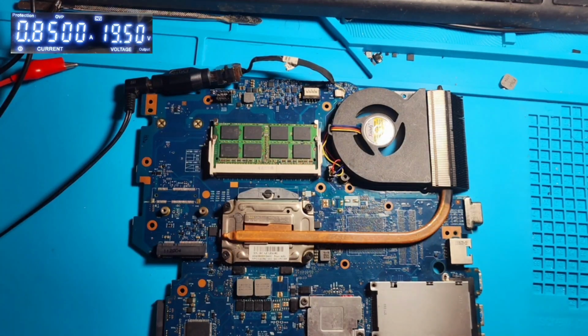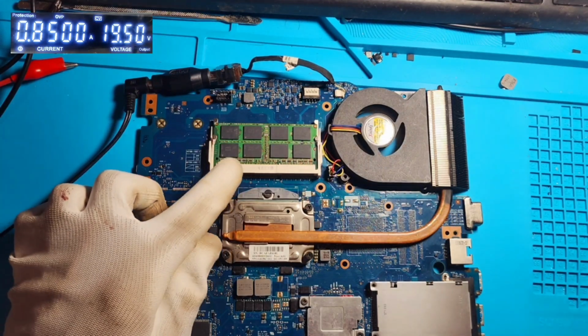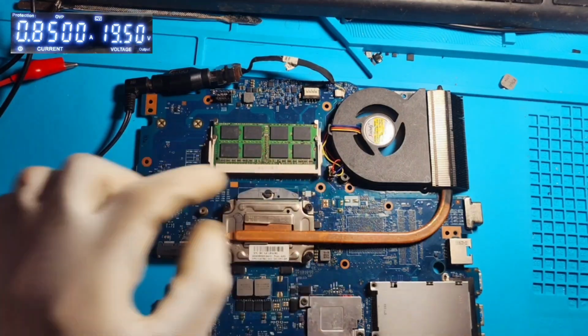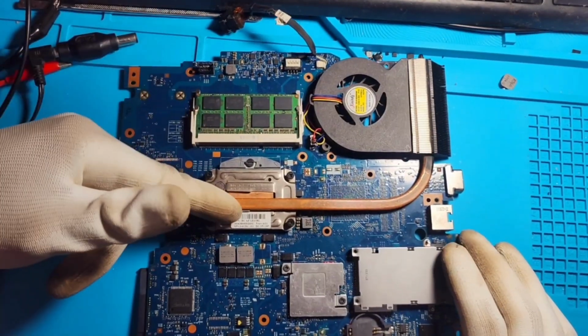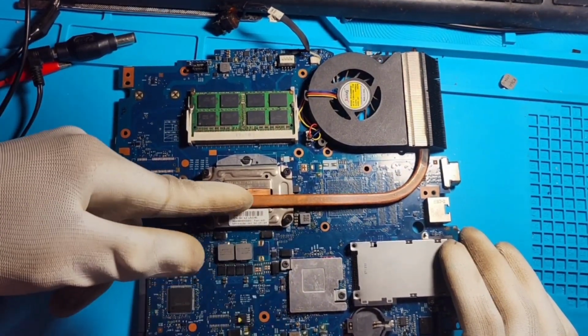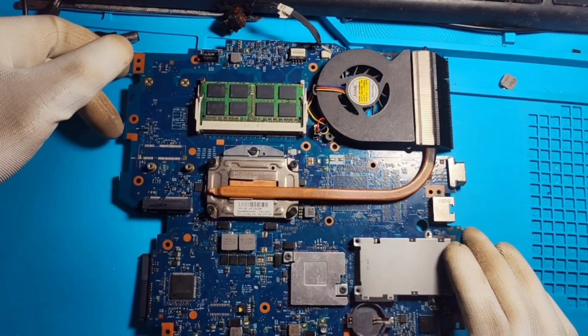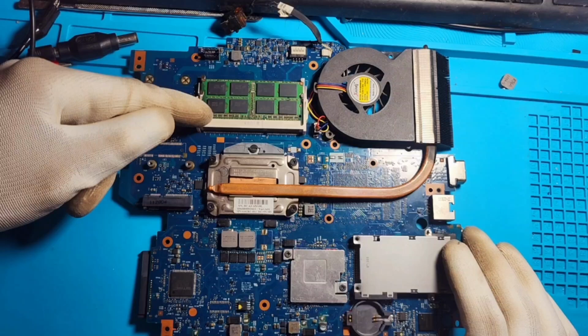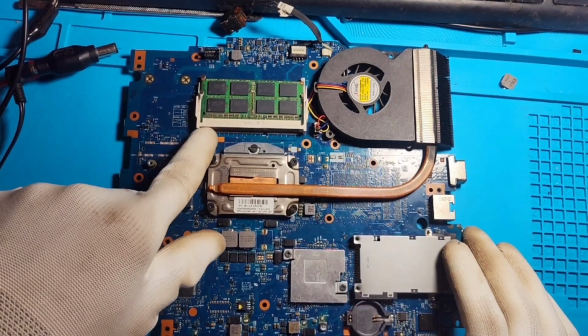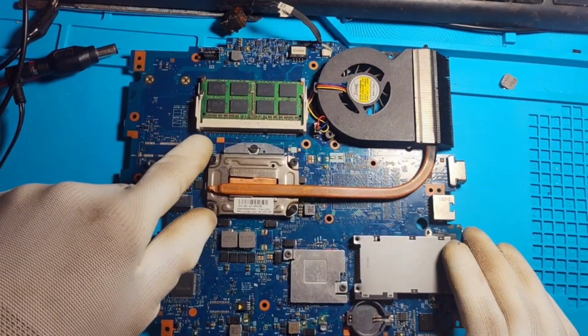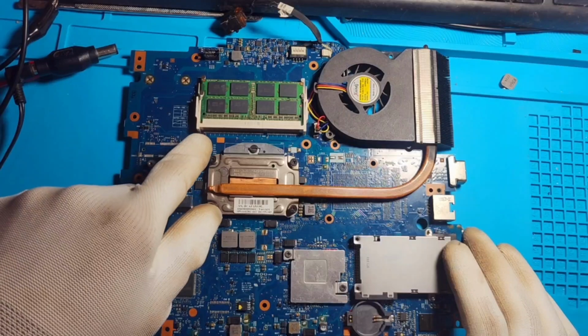So what we have to do is check up on these RAM slots. How does the CPU or the PCH detect whether the RAM is connected to the board? It is detected through the SMBUS line. There are two pins going into the RAM slots, known as the system data and system clock lines.